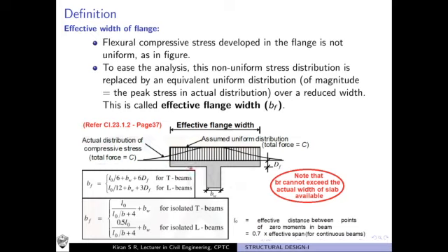You see, this is a typical T-beam, and you know every beam when subjected to loads will experience compression in the region above the neutral axis. So if here is the neutral axis, the region everywhere above the neutral axis will be subjected to compressive force. But what about the region associated with the slab?